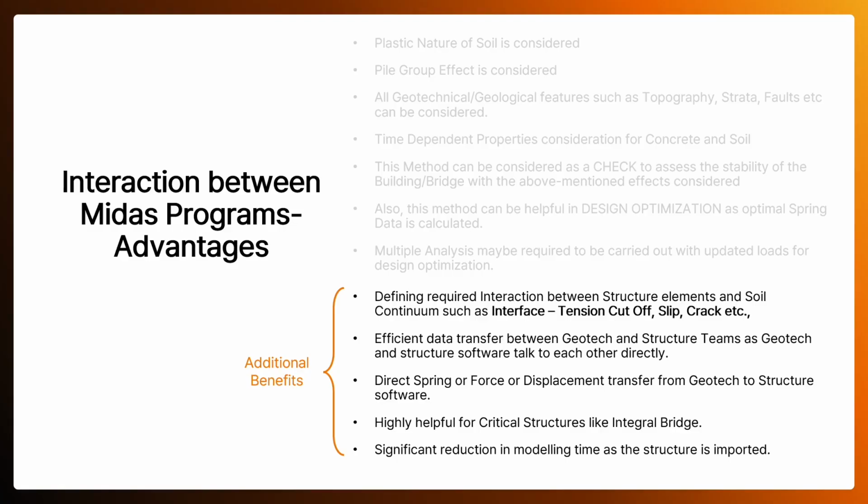And as I said, there is the transfer of the spring stiffness and the force displacement curves between the software. For critical structures such as integral bridges, this plays a very important and key role, because the integral bridge is a structure where you have two places where the soil comes in contact with the structure. So you have the pile soil interaction, you have the abutment soil interaction. Both of these have to be considered.